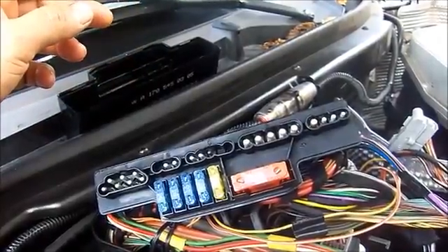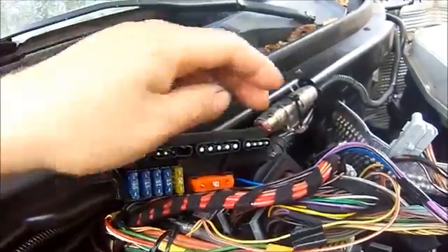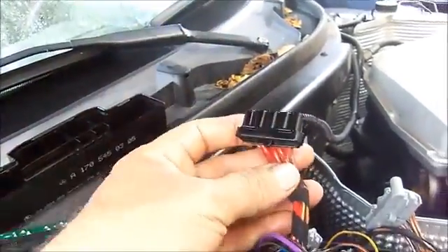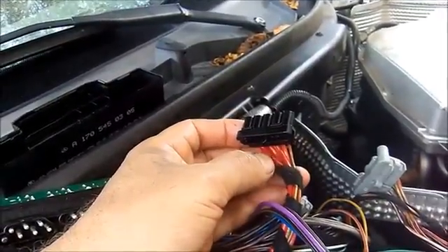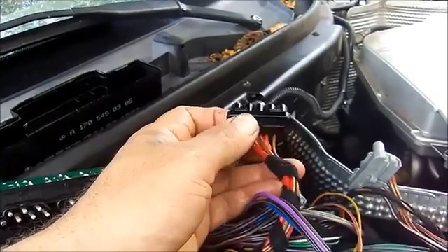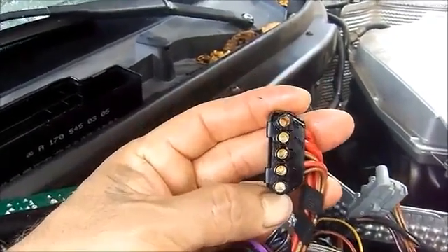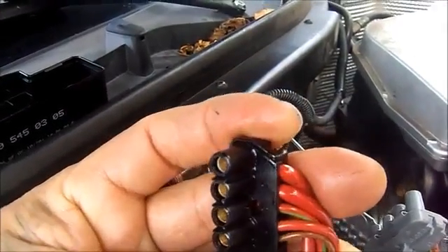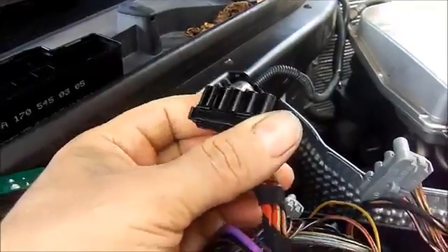No communication. TCM, PCM, found some transmission fluid, and it does travel through the wiring. I've seen this before on old Mercedes vehicles, and actually this Crossfire has a Mercedes 722.6 transmission unit in it, and whenever they leak through there, you see the same issue. See that transmission fluid? I'm going to go ahead and clean this out and see if we get communication with it now.